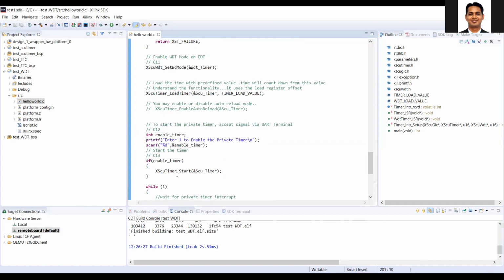And then we will remotely restart the board to indicate that now the reset has happened because of the actual restart. And you will see that when we sample the status of the reset, it will show that the reset has happened because of the actual restart and not because of the watchdog reset.